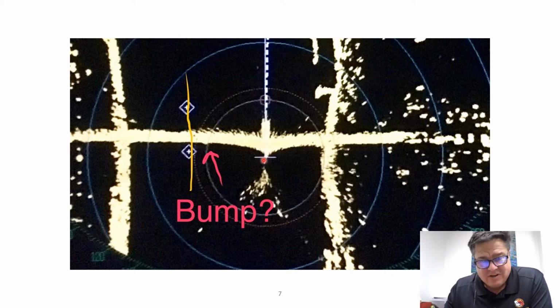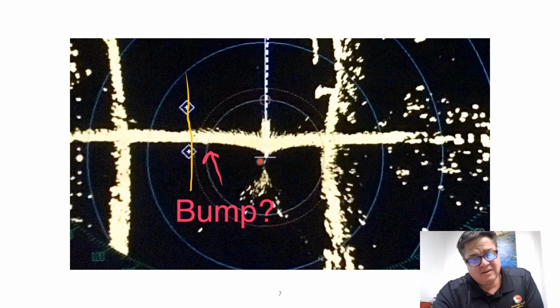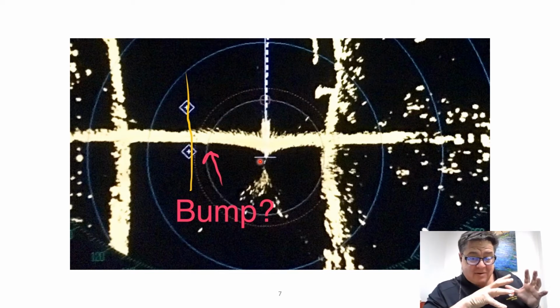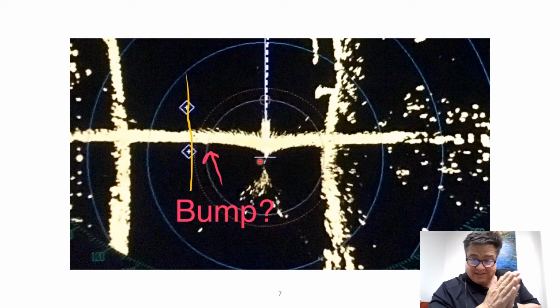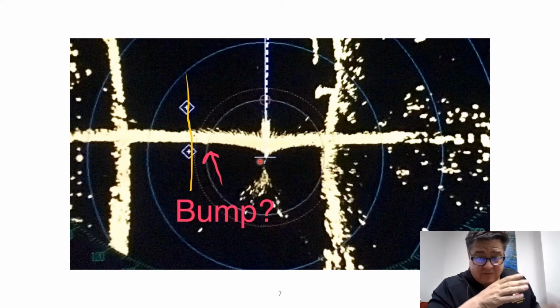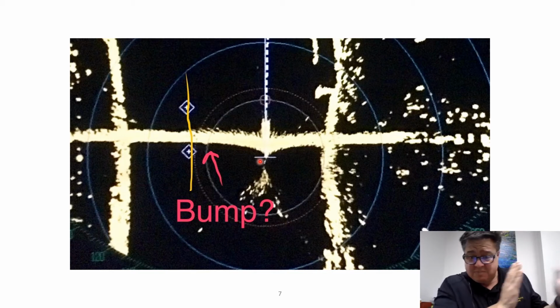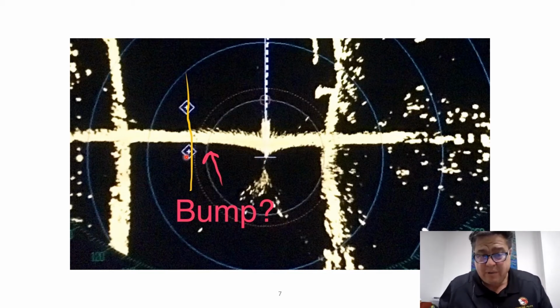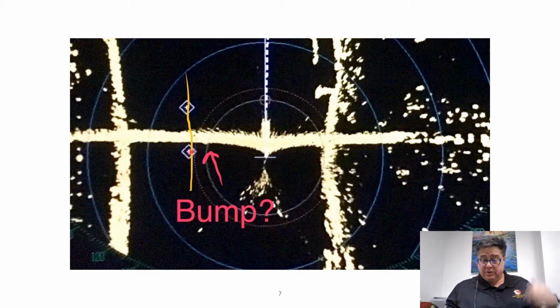So you have to have an assumption that this GPS position is accurate relative to this GPS. If this one isn't known right, because maybe the consistent common reference point isn't so consistent on the ship, maybe they didn't set up their integrated bridge so that everything is synced up, and the radar is aware that the GPS antenna is way over there, and so that gap distance is being transferred to all the other measurements. That's a possibility too. We just don't know. But I know it's not right, and you have to be careful.